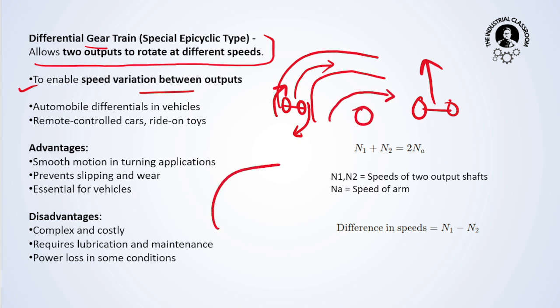Okay, for example, see this. This is my path. Now you can see that this radius of curvature is very less. So here you require a slow RPM whenever this wheel needs to move, and then again you will go straight. The rear wheel or the left side wheel will need to cover this distance, but this will need to cover a very small distance. Then again they will go to the straight path and they will go along. So these are used in vehicles.